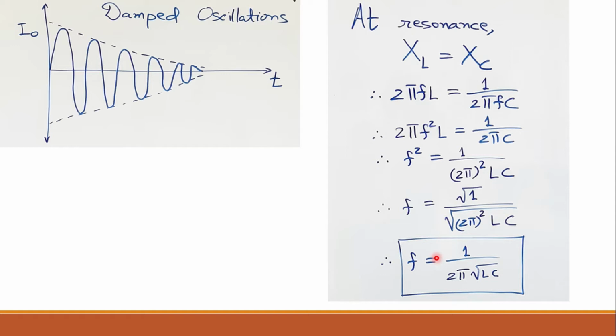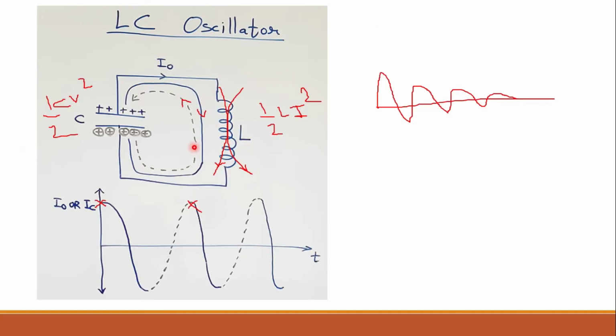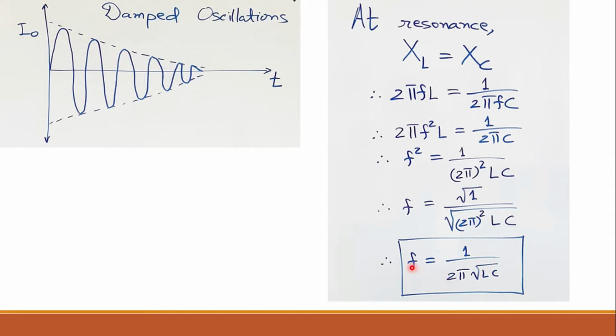Now what is this resonant frequency? This resonant frequency is the oscillation of a system at its natural resonance or unforced resonance. So that is the resonance frequency. This LC circuit which we have just seen is also known as a tank circuit. Why is it known as a tank circuit? Because it stores energy as you store something in a tank, therefore it is known as a tank circuit. And it is also known as a tuned circuit. Why? Because for receiving the waveforms of this circuit you have to tune to this particular frequency of this circuit, and therefore it is known as a tuned circuit.